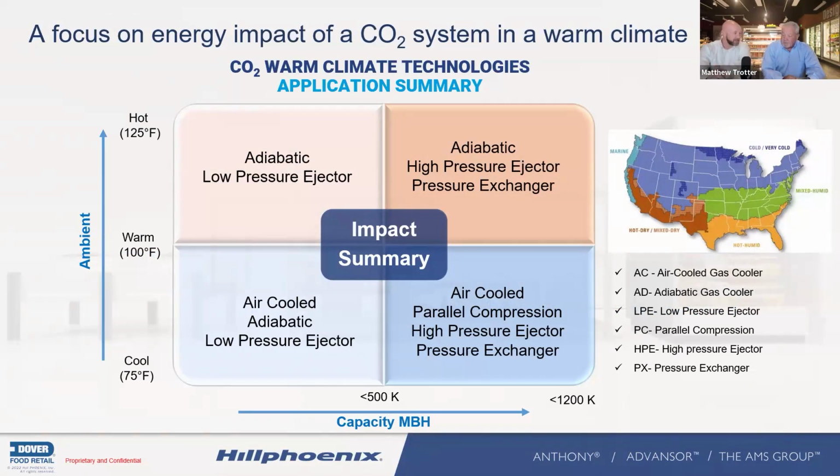So I had a question. Actually, as you're going through. When we first started this out, knowing what I know of CO2 in warmer climates, south of the Mason-Dixon line, I live in the south but I'm from the north, so I know both climates. At first I thought we definitely need to get to that change of state. My refrigeration background takes me right to coming out of the gas cooler, the condenser if you will, and trying to get to that change of state. But we also have the flash tank that helps us with the drop in pressure.